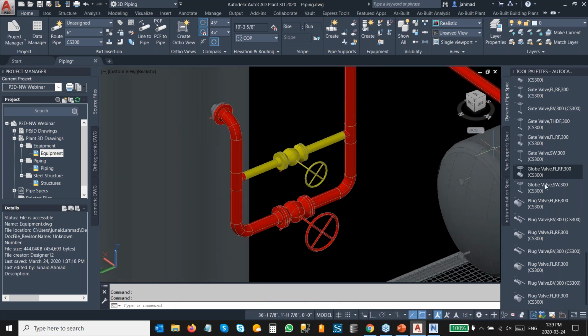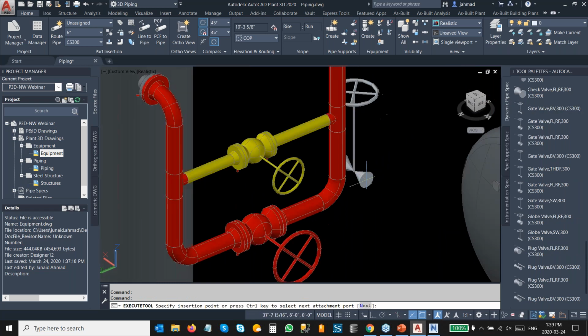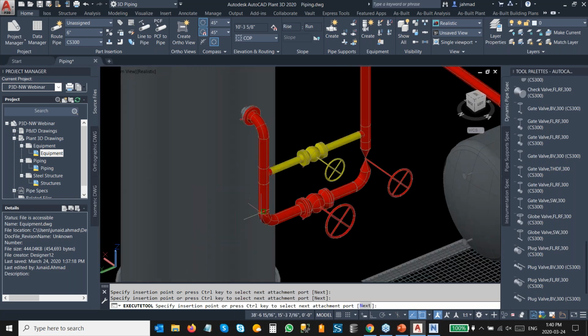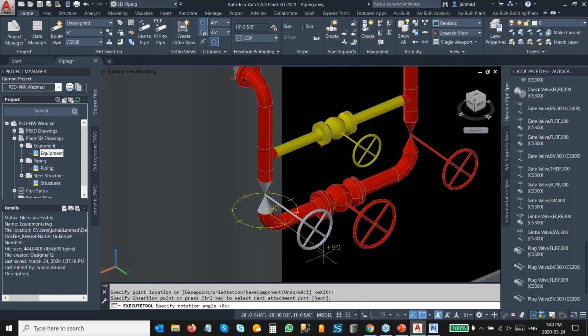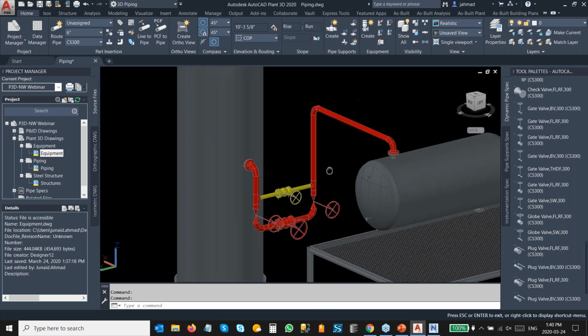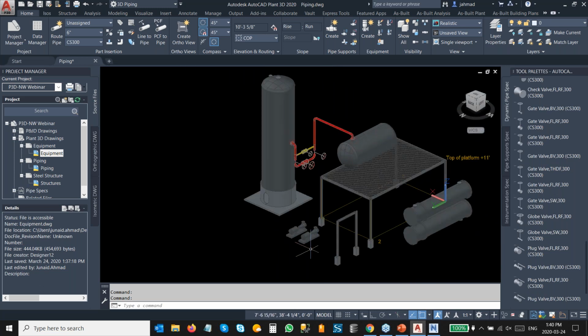of the pipe. I'm going to end this pipe run by placing a couple more valves here. So one over here, and then I'm going to draw another one here, and that pipe run is finished. Now, if I want, I can start assigning all the properties and the tag numbers to the valve and the line number in case I want to see that on the ISO drawing.